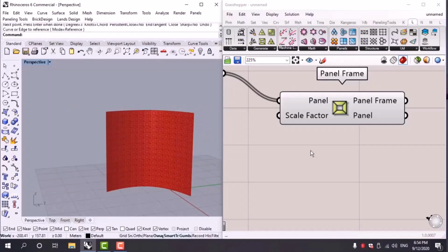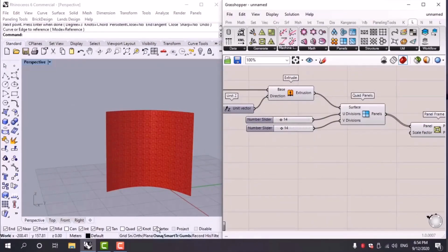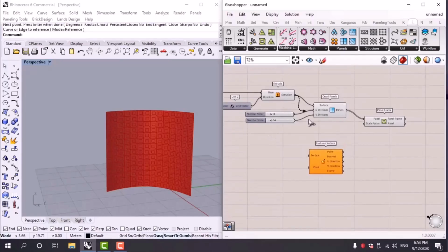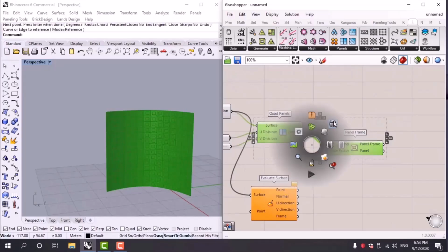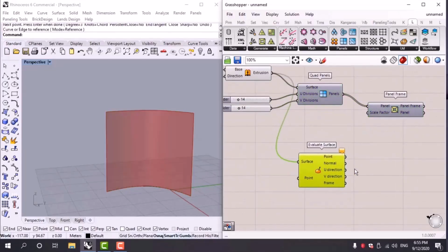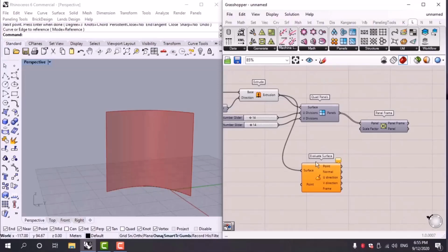So to do this, at first we should create a point on the surface. Let's check it out. To create a point on the surface, at first we should give the U and V directions. So we got a tool which is Evaluate Surface, to evaluate an expression with a flexible number of variables. Firstly, we give the surface this way, and then by specifying the directions of U and V, we can have the point. I select these to hide their previews to explain the Evaluate Surface command.